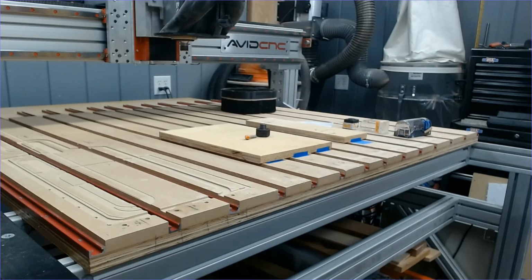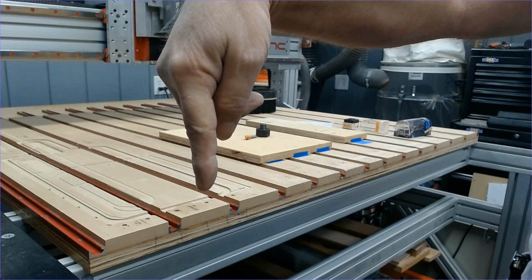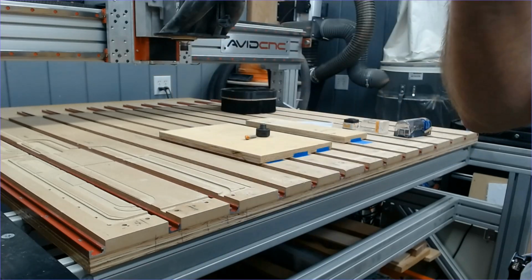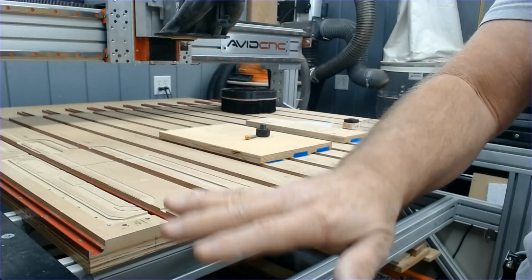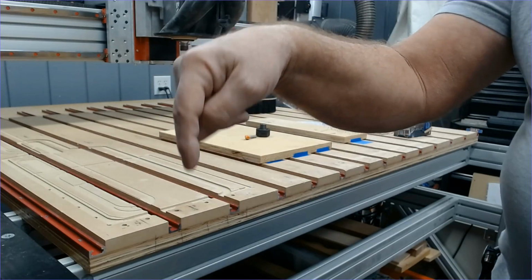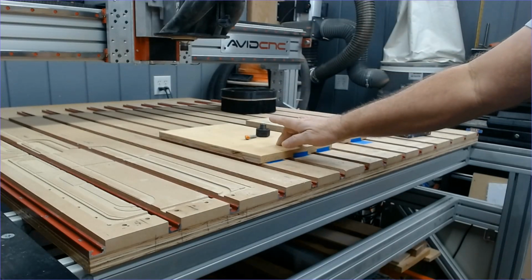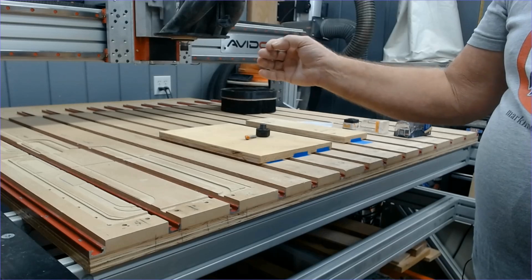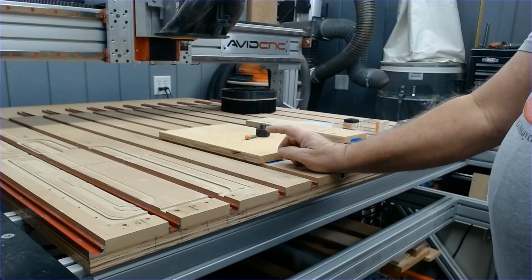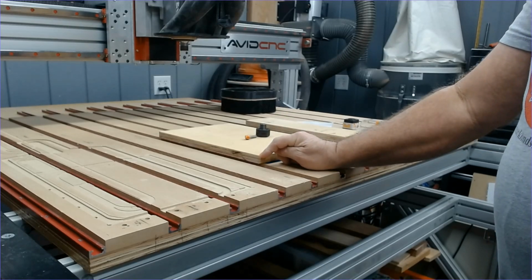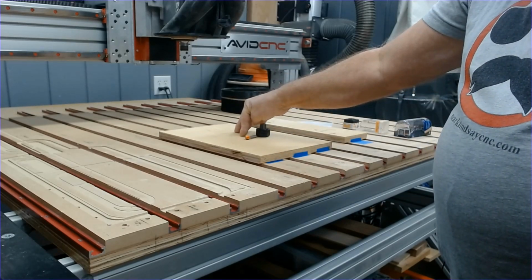of the machine. If I were looking at this from above, this is the bottom left corner of my CNC router. That is X0, Y0 in machine coordinates. And all coordinates after that are in reference to this corner. In work coordinates, when we set our XY datum position in the Vectric software, they were in reference to either the bottom left corner of this piece of material or the center of this piece of material.